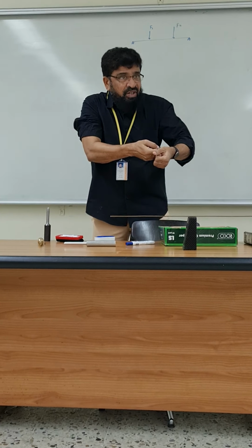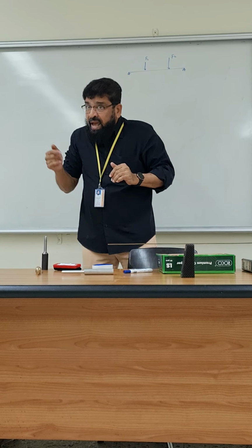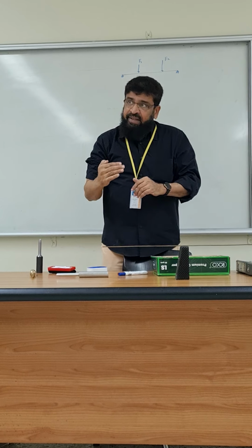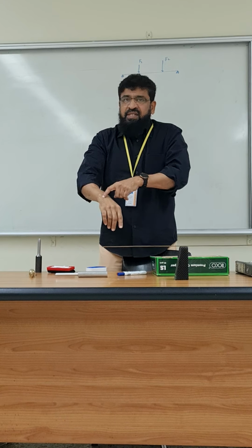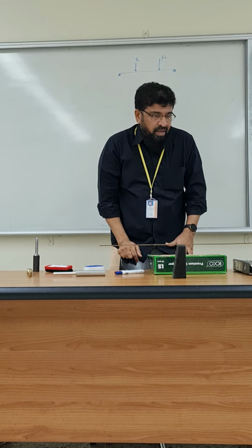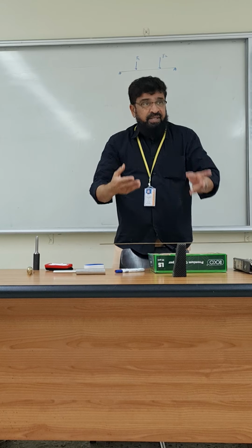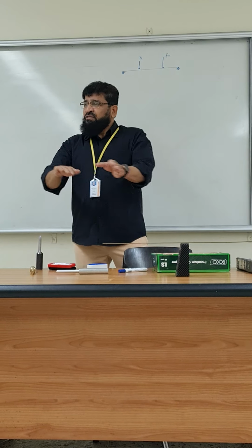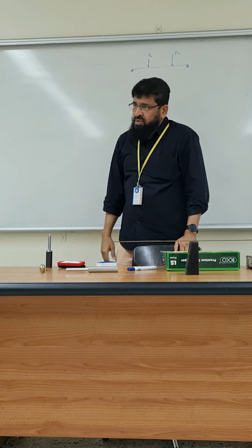Because of this, you have got tension in the bottom. In the top, you have got compression. Is this clear? At some point, there is no tension and no compression. Where is that layer? All these things we need to find out when we do the design. These stresses are called bending stresses. Because of this bending, we have got bending stresses in the beams. This also we need to study. Before that, the first one is bending moment and shear force diagrams we have to draw.